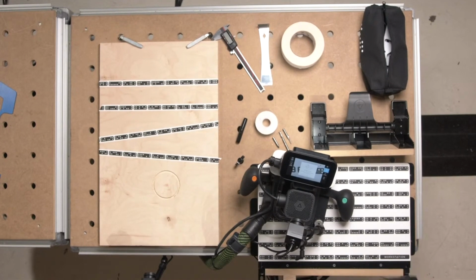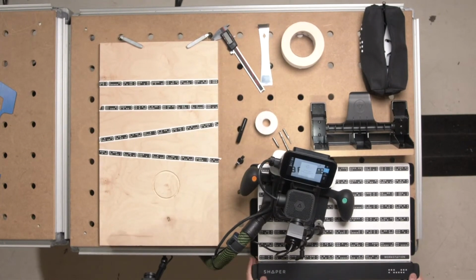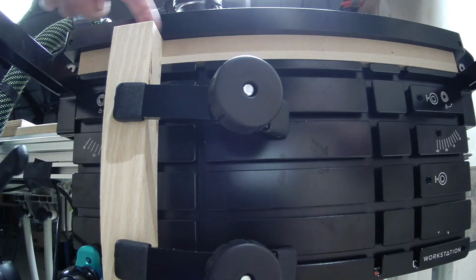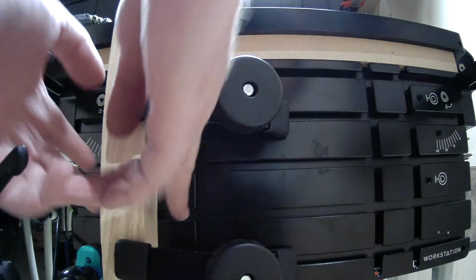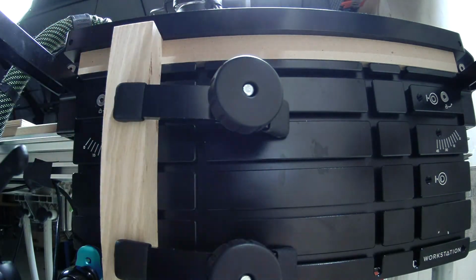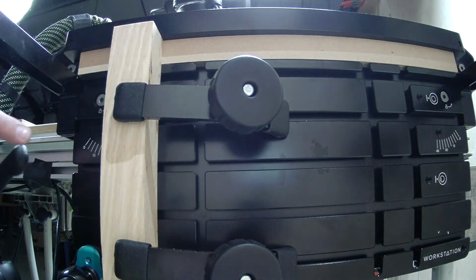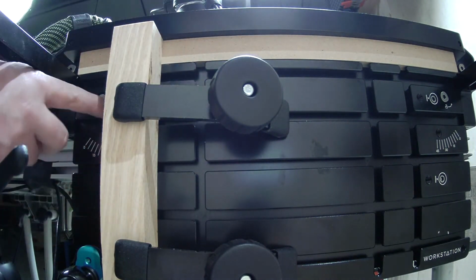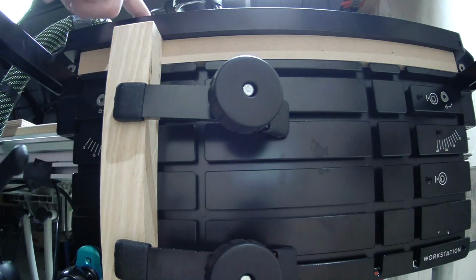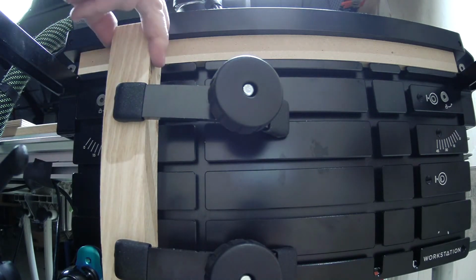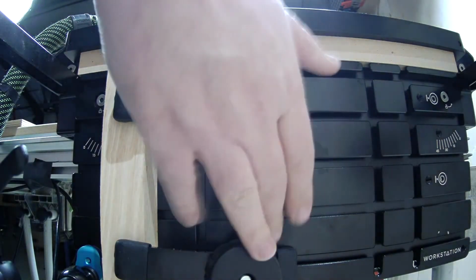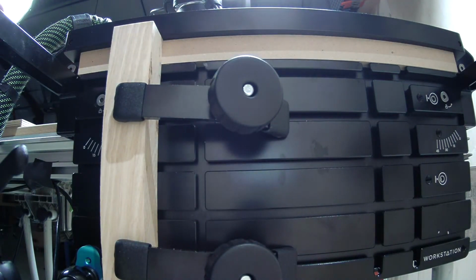There are these neat little features in the workstation, and you can look at your manual to see a little bit more info about this. You can actually put the support bar in those features, and it acts as an in-stop up here for your work, so you get that really dead-on level with the top of your workstation. So when you're clamping everything in, you put that guy on there, and then it's really easy, because you've got your alignment pins on the left side of the material. You've got your in-stop on the top. You just push it into those three points, get it clamped in, and it's going to be aligned perfectly.